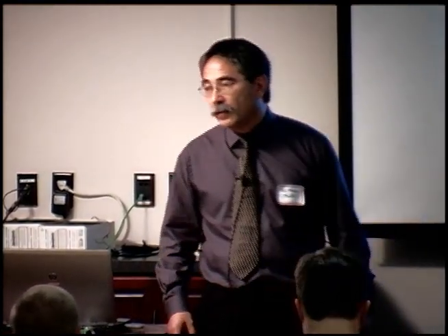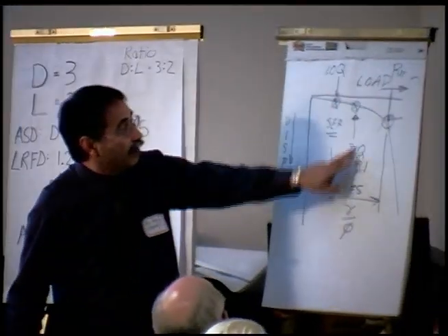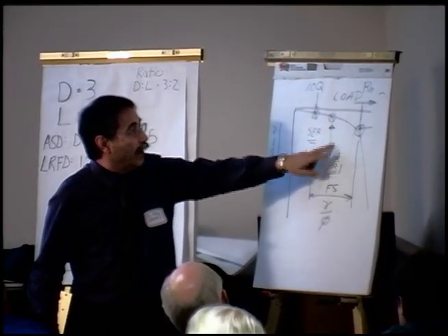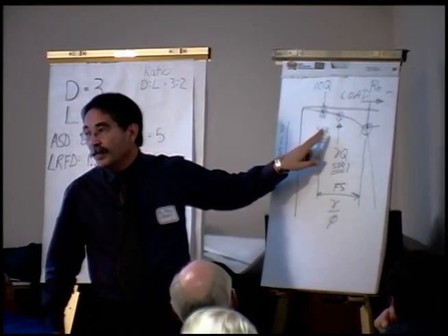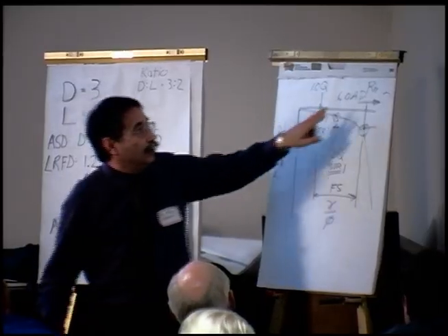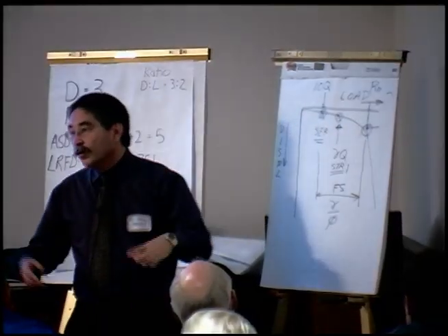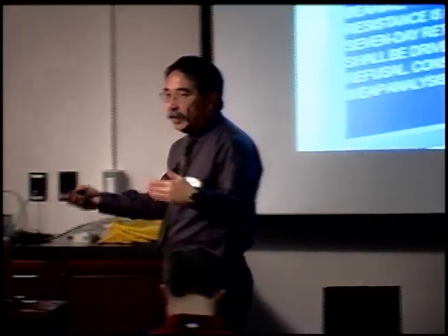You're saying in design you need 197 kips per pile. Right? Correct. In design, we need 197 kips. And where that came from was from the structural side of the house. It says I got 128 kips, a factored load, which we said was, if we just took it and divided by the average load factor, the service load, say in the neighborhood of 80 kips, right? And when we add in the resistance factor to get the nominal capacity, we needed 197. No matter what, as long as I provide enough resistance capacity that exceeds the demand.